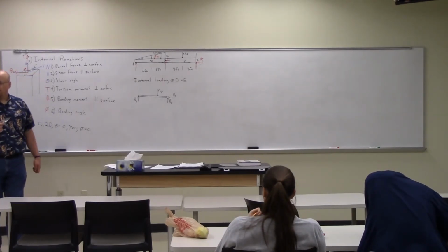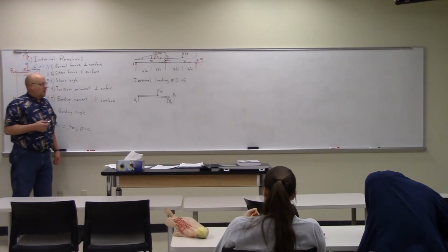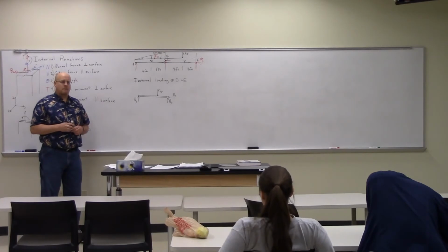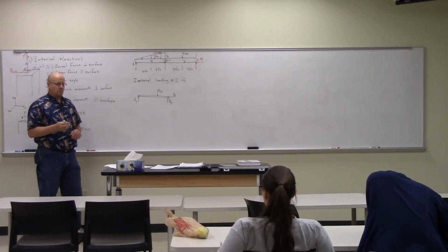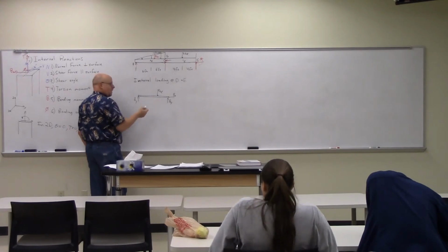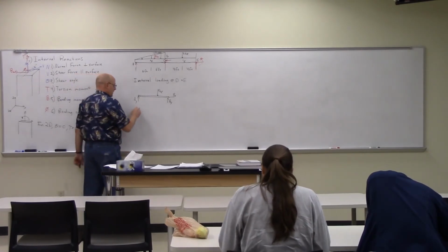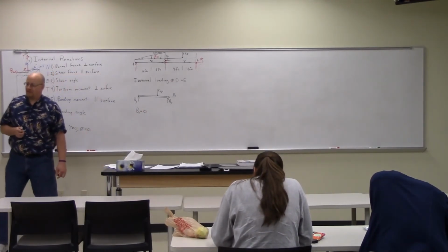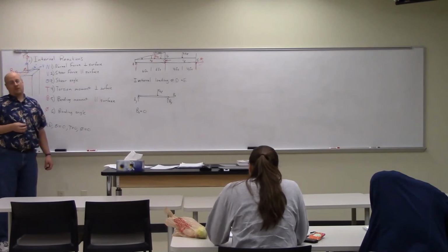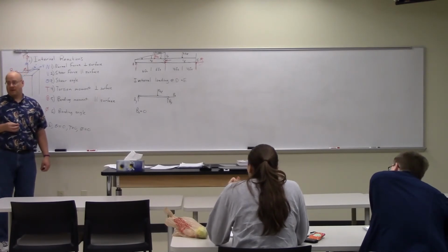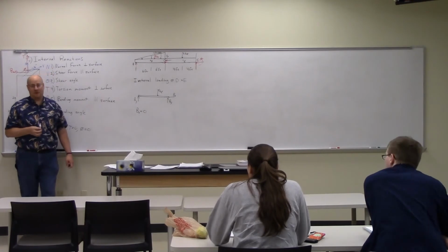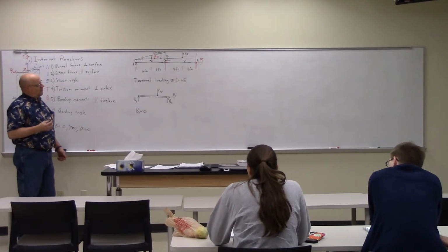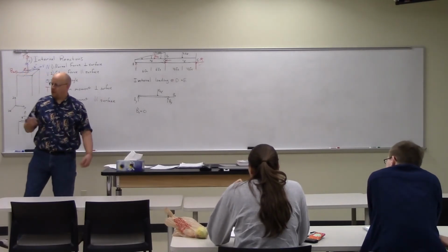Sum equals 0, so the sum of your moments and forces equals 0. All right, so what do you want to do first? Well, the X is the only one in the X direction, so you can sum the forces in the X direction. Okay, so we look at it, and by inspection, identify that Bx is equal to 0. If you say by inspection, you better make sure that it's legit. You don't look at the picture and say, oh, well, by inspection, D equals 6.24 kips.